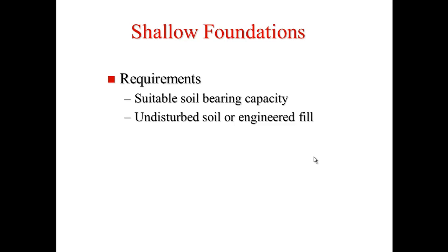If you dig down one part of a foundation to a point where you're going to set your footing and leave it alone, but on another side you dig a little too far down and you have to build it back up with some fill that's brought back in, it's never going to get compacted to the same amount as the undisturbed soil, because that stuff has been sitting there for many years, hundreds of years, and it has compacted pretty much to its full amount with all the changes in weather and whatnot. So always excavate to undisturbed soil.